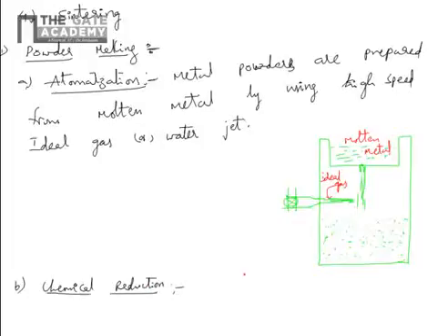So here we reduce the metal oxides with hydrogen, using a chemical, especially oxides. You know that aluminum oxide will form these fine metal particles. So reduce metal oxides with hydrogen. It's a chemical reduction process, which is one of the methods to prepare metal powders.